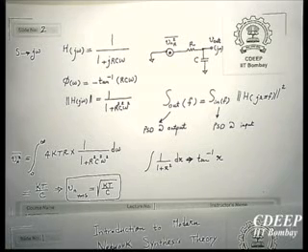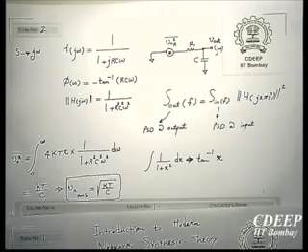So interestingly, it is independent of R. Intuitively, you can see the reason: if you increase R, then the RMS value of noise in the resistor increases. However, at the same time, the bandwidth of the filter reduces. Therefore, you are increasing the power spectral density of noise, but you are reducing the bandwidth of the system. Therefore, it is expected to be independent of R, because both will cancel out each other.